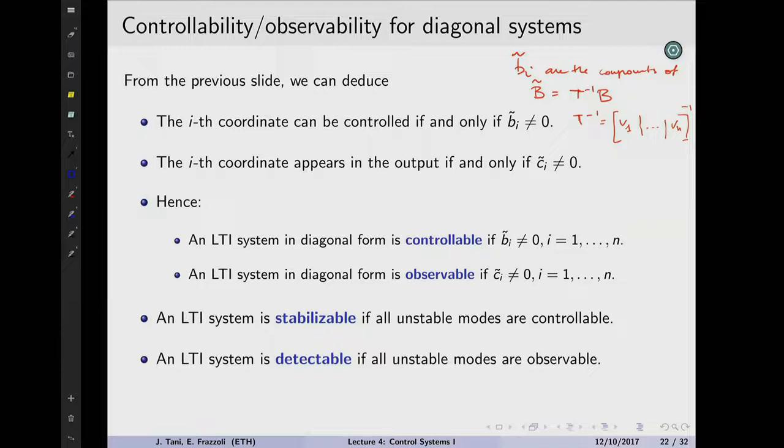Controllability, as we defined it, means that every single state is controllable. We don't really require that. We require a system to be stabilizable. Stabilizable is a word we use to define a system in which the subset of the modes that are controllable includes at least the ones that are unstable. Okay, we will continue next time.